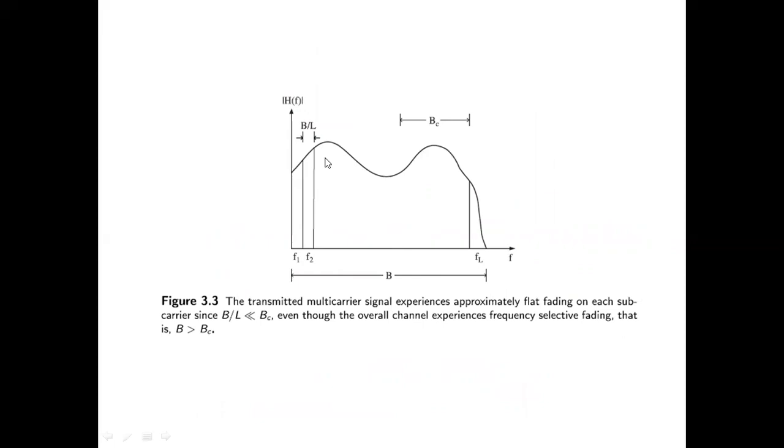So you take IFFT so that you have these individual very narrow width channels, individual narrow width data, which will fit in a bandwidth less than your coherence bandwidth, so that you can tackle the errors easily by going for error control coding, frequency domain equalization, all such stuff. So this whole method is used for tackling the fading, for tackling multipath fading.